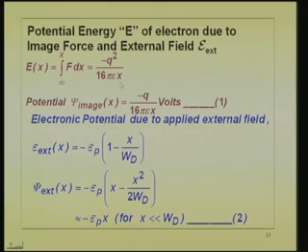and you get that. Now, the potential of the image. In fact, electronic potential is, you remove that one q from there, since energy is q into V. I am just finding the electronic potential, which is the same variation as the energy band diagram. When you see the plot, it will become clearer. So, I remove that q there, it becomes potential. Energy is q into V, I remove the q, it becomes potential. That is what happened there. And the minus sign is there. Let us go to the next diagram and see.